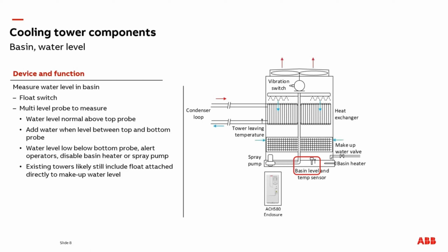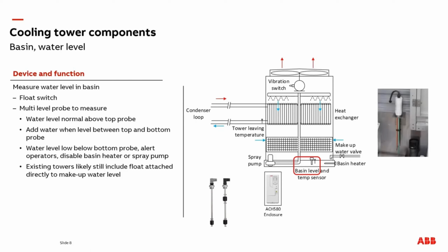For fluid coolers, the spray pump will draw from the basin to spray nozzles above the heat exchanger for evaporative cooling. For proper operation, the basin water level must be maintained. The water level will be measured with either a float or a level sensor. This can be used to open up a makeup water valve to replace water evaporated, enable a spray pump, or a basin heater for cold climates.